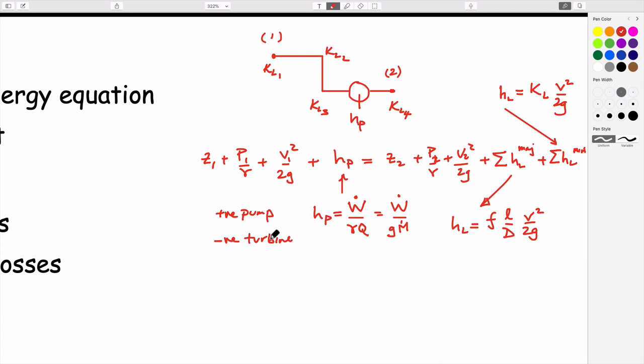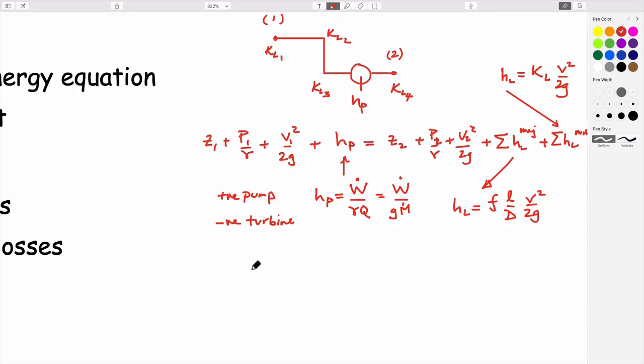So that's kind of a fundamental relationship for us. And in this, if we were doing this, then we would have loss factors for each of these minor losses within the system. And if within our system we are able to define those, then we would use this expression, and the sum of head losses which are minor would be equal to whatever the head loss KL1 was.